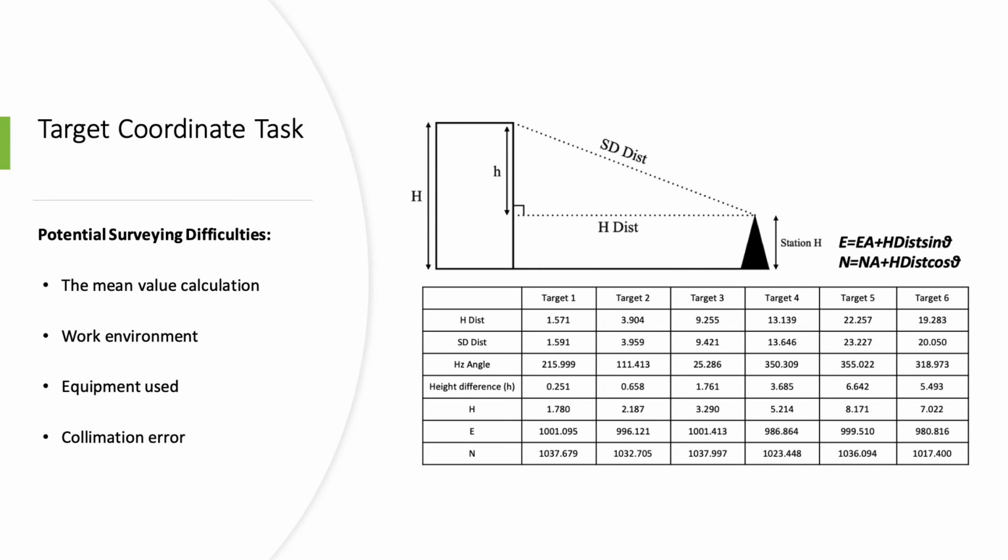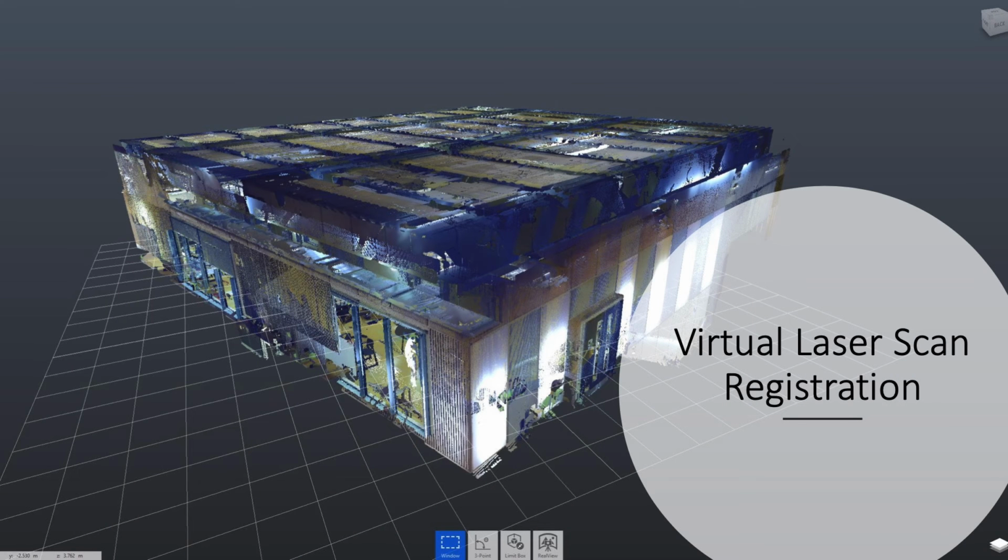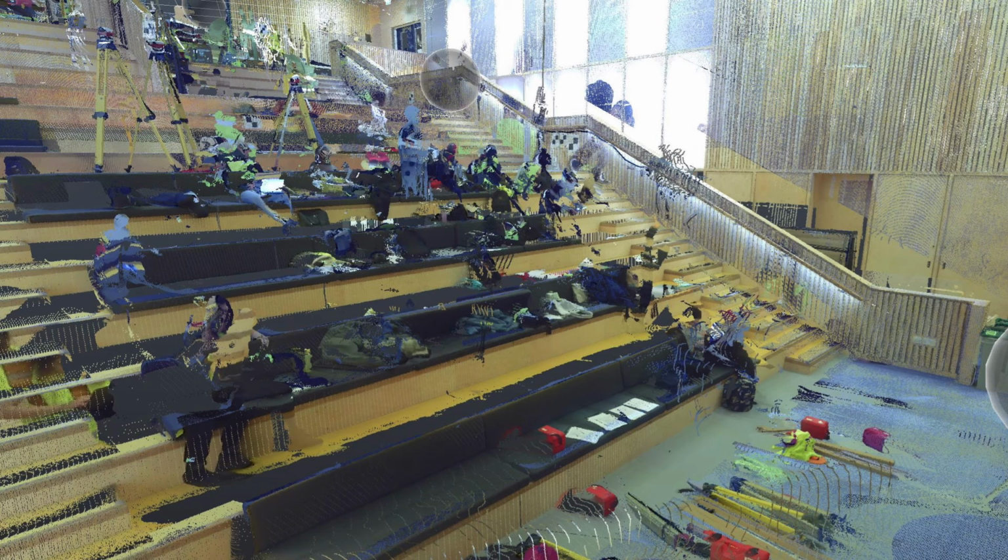7 pieces of laser scan data were imported into ReCap and auto-registered to create a merged point cloud model of the Here East lecture hall. Targeting adjustments by manually selecting the positions of the target sheets on the walls was tried but turned out to decrease the quality of the model, so the step was undone and the model created by the auto-register was kept. Extra points outside the regions of interest were deleted to make the model smaller and cleaner.